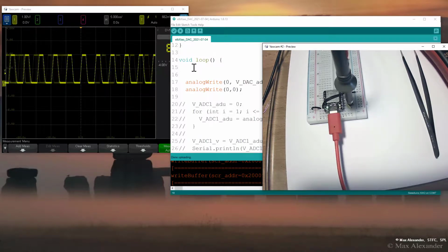There may be a case where there's poor communication over the USB ports, in which case I think just rerunning the code works fine. Every now and then you'll get a 2-bit error in some of the communication back and forth, and that will hang it up. Unplugging, plugging it back in will fix that problem. That's different from bricking. If you lose port information, then you gotta do this reset trick, and that will reset the Xiao module back to factory default, and it will understand how to talk over the USB port.